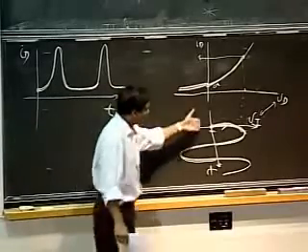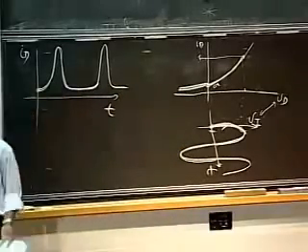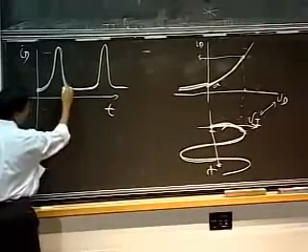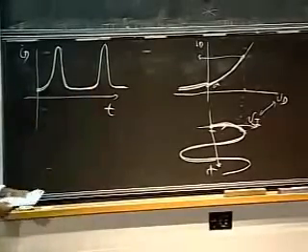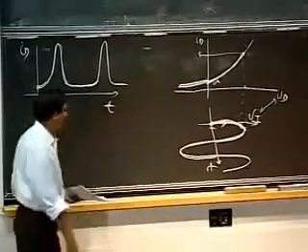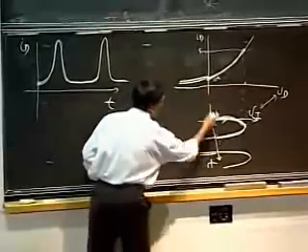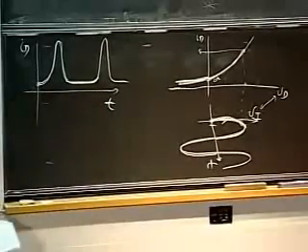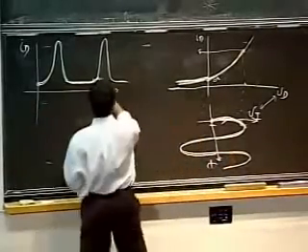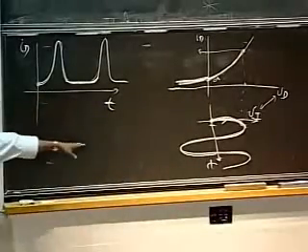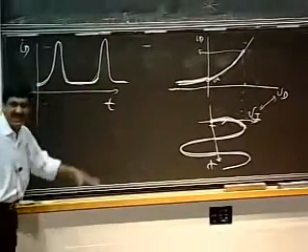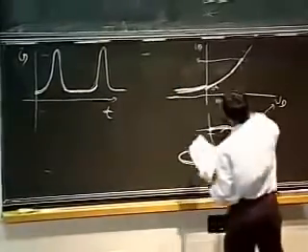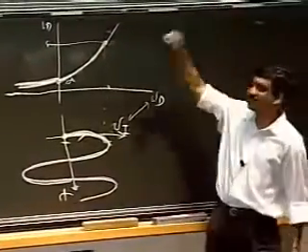Notice that this device has completely cut off and hammered negative going signals. Okay, what it's done is that rather than giving me a nice little negative spike excursion here, what this is doing is that it's taking this excursion and simply slamming it down to this value here. Okay, and then again, when I go back up, I get this peak here. So notice that what was a nice little sinusoid out there gets hammered and squished into this funny curve here. Okay, what this device is doing is for positive values, it tends to produce exponentially greater current.